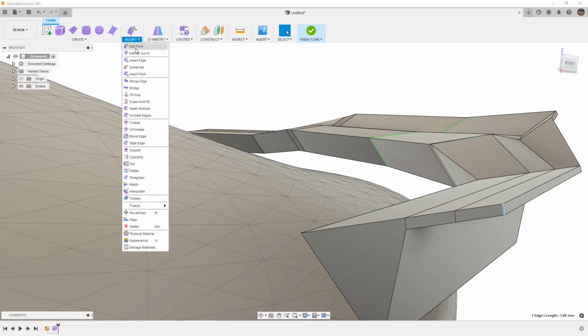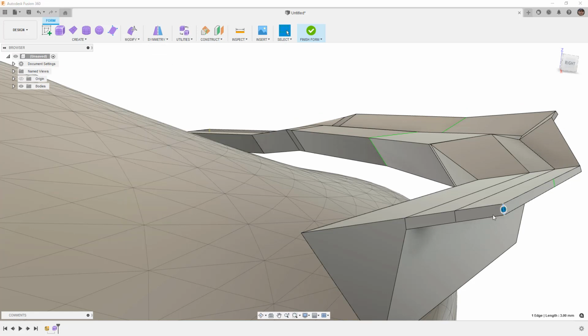So I'm going to take one edge, I'm going to go to Insert Edge, and notice that half puts it way in between that face, and I need to bring that way, way back. So if you want it to be a pretty tight transition, it's going to have to be pretty close. I'm going to repeat that process using my right-click marking menu, and I'm going to put it on this side, and again, pretty close. Now the trick here is that this has to carry somewhere.